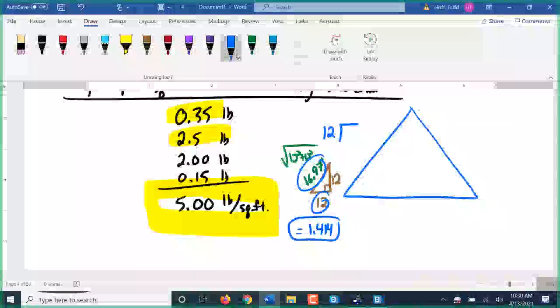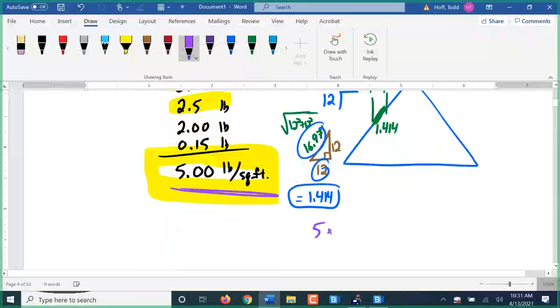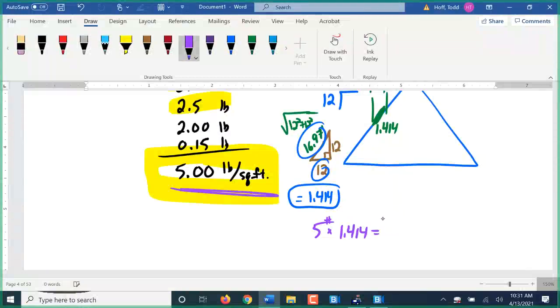So the amount of shingles, we would figure this as being 1 square foot. 1 foot in this direction, then of course 1 foot along towards the direction of the ridge. But it's really 1 foot wide by 1.414 feet up the slope, which means the actual amount of roofing material on that is not 5 pounds for the sheeting, the shingles, and everything else. It is actually 5 times that slope correction factor of 1.414, which ends up being 7.07 pounds.